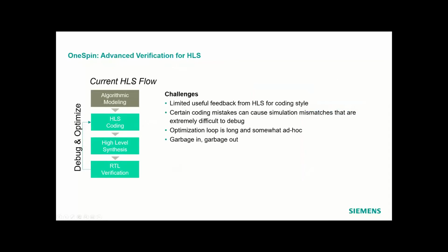Okay, so currently in the EDA industry, when companies are using SystemC as a language description for their design, the current HLS flow looks like this: generating the algorithm model in C++, then getting the HLS code in SystemC or C++ that is synthesizable in hardware, then importing that HLS code into high-level synthesis tools, and then the high-level synthesis tool will produce the generated RTL.